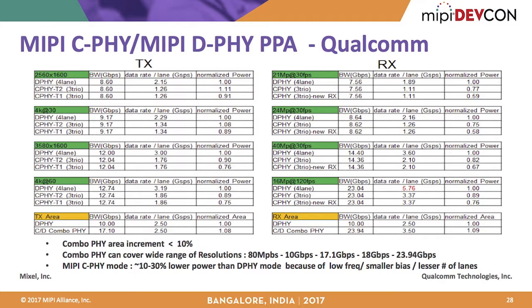But as of today, in order to do that, lane speed has to be 5.76 gbps for the D-PHY case, and it's not available. But we can go with 3.37 gigasymbols per second for C-PHY because of the encoding, which is available. So that's one of the advantages.